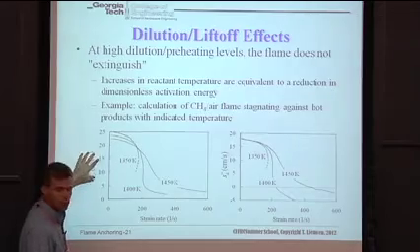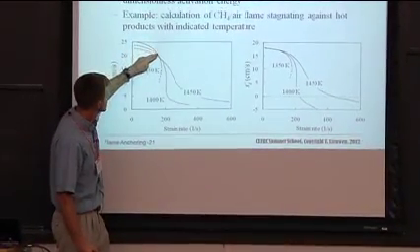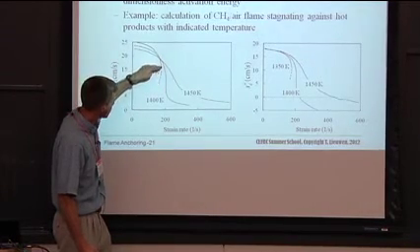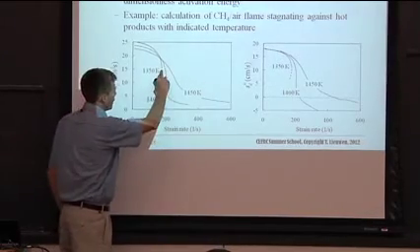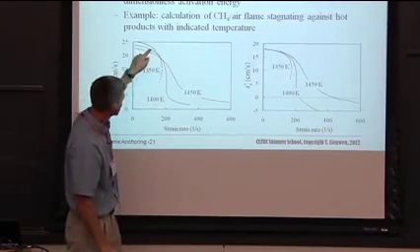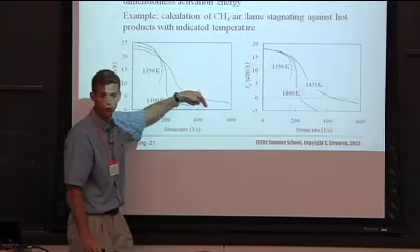And as I talked about, as you increase flame strain rate, this is the consumption speed. This is the average burning, the average consumption of reactants. What happens is it drops, and then there's this critical point when, bang, I drop to zero. So the flame very abruptly extinguishes. And this dashed line just denotes the unstable lower branch. But what happens is that at about 1400 K, you lose this tangency point. At 1450 K, you basically lose your S-curve completely.